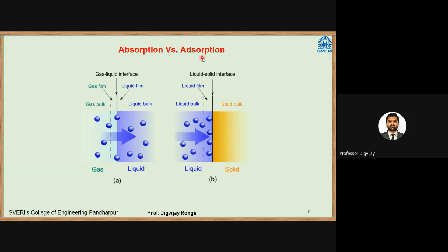So that was the case of adsorption. In absorption, the gas will diffuse inside the liquid. As in our case, we are using aqua ammonia solution. So in this case, whatever ammonia vapor is there in our system is absorbed by the water. Also, I have shown you one video of the ammonia fountain. In that case, ammonia is absorbed by the water. A pressure difference is generated. To compensate that pressure difference, water is ejected through a tube and we get a fountain. So those who did not see it in the last lecture can Google it, or you can see the videos on YouTube also. Ammonia fountain. Okay.